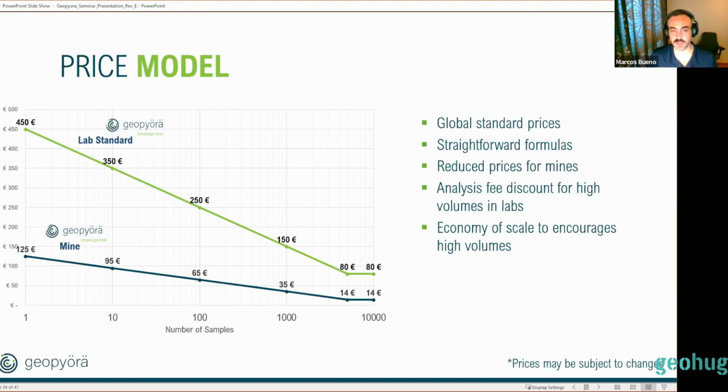They only crush it to subsample it, then pulverize it and do a geochemical assay, either through ICP or XRF. And we want to propose using the same samples to change this paradigm, where you test tens of thousands of geochemical assaying samples and a handful of comminution samples, and you have a huge uncertainty on the hardness of the rock.